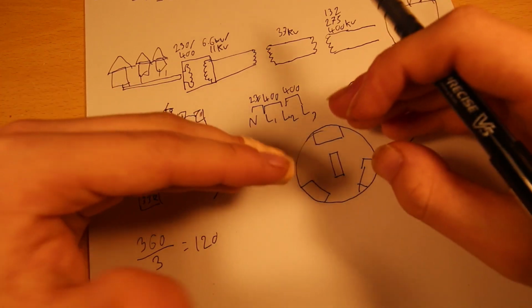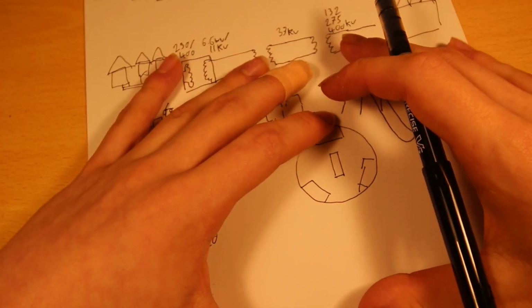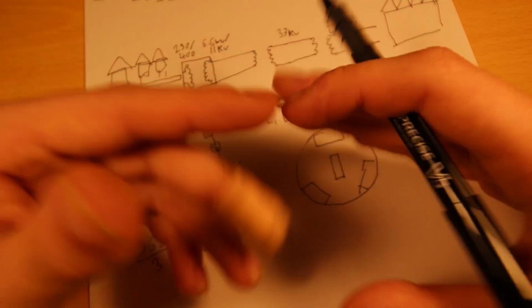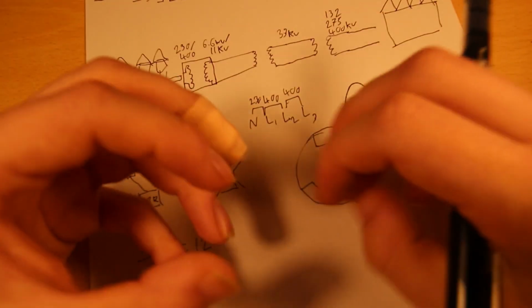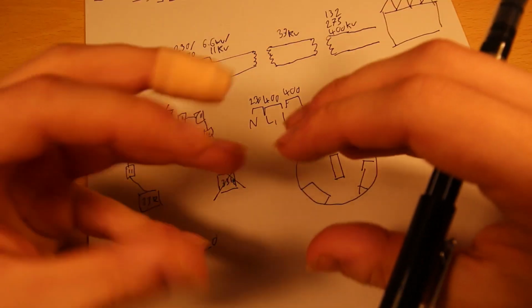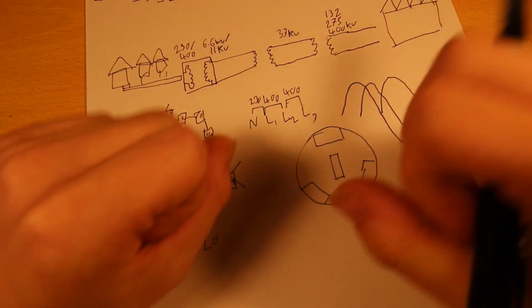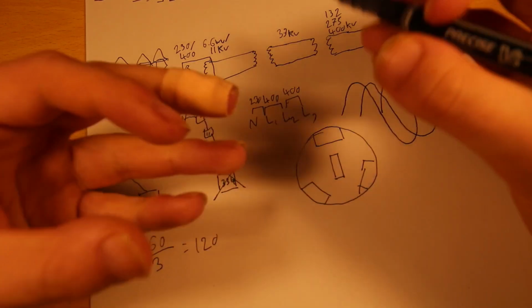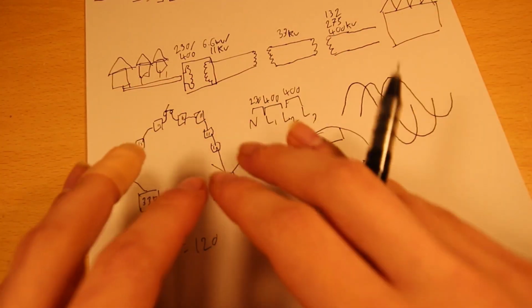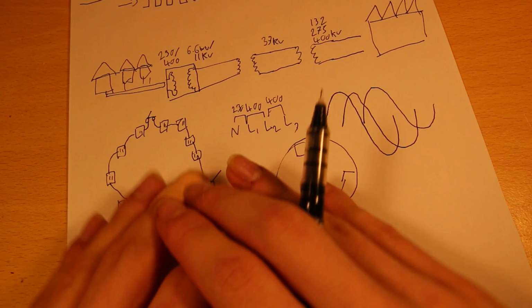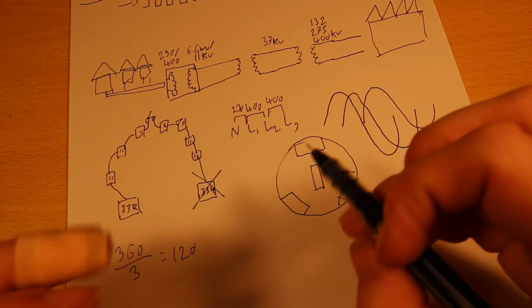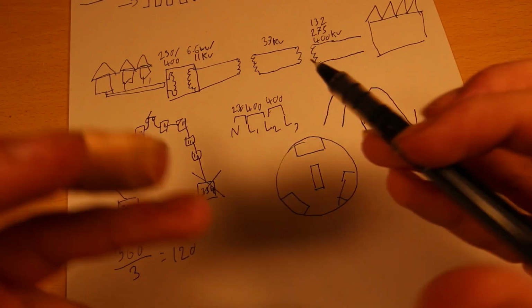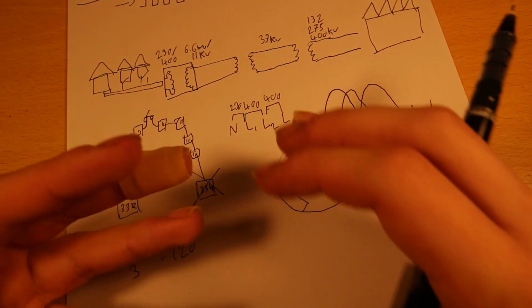They rectify it and then they can't smooth it though, because, again, I'll get into this in future videos, there's a thing called inrush current, and when the train starts up, it draws so much power they couldn't smooth that out. So what they do is they take the 3 phases, and using the black magic of transformers, they make it into 12 phases, and then rectify that, which gets you a much smoother output even under extreme loads.